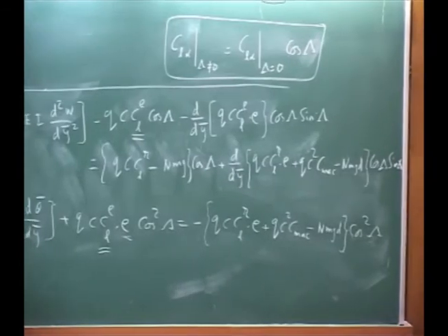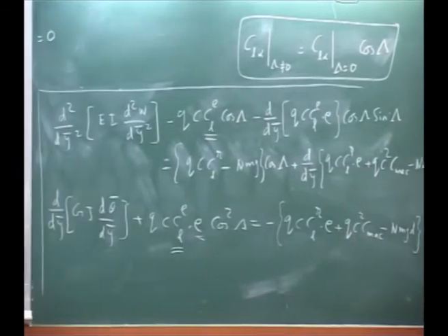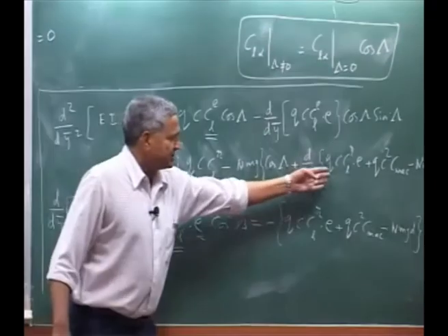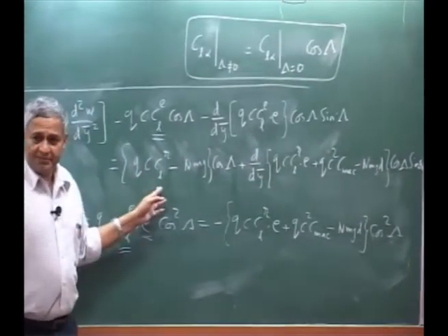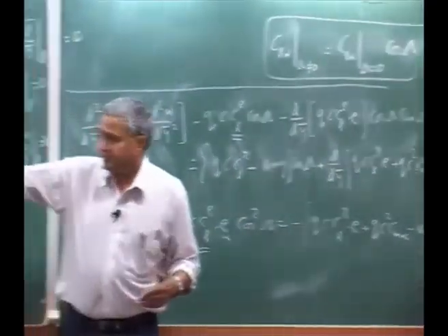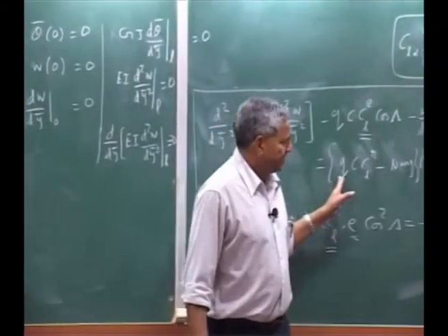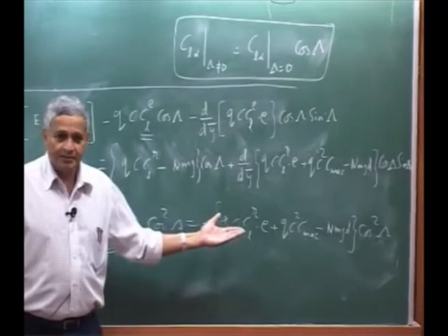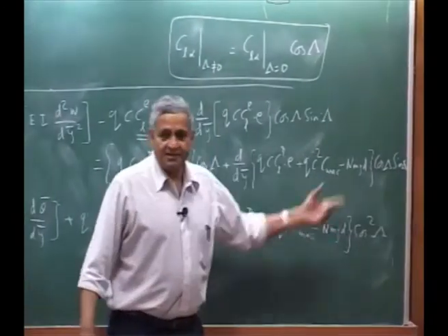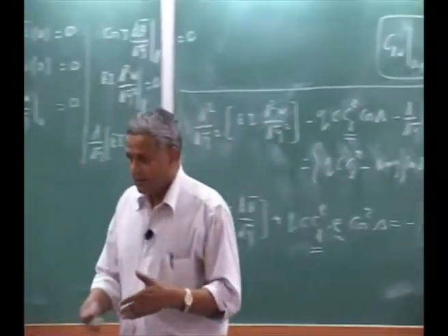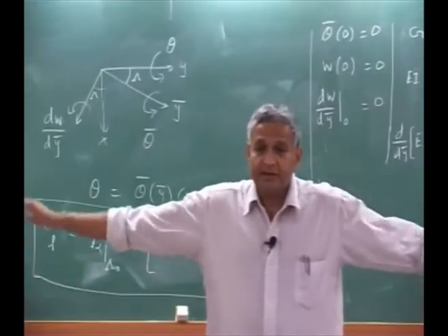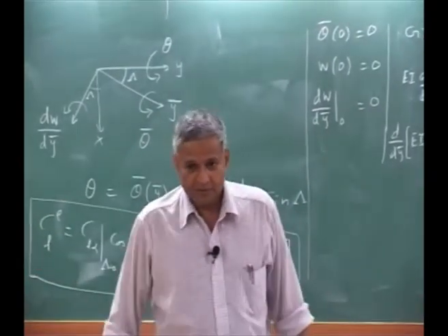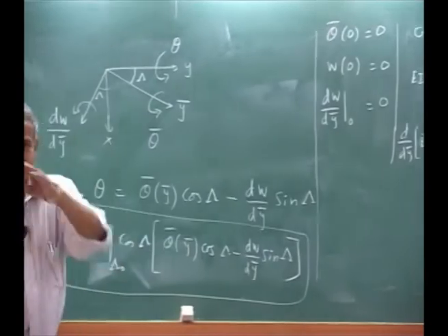Otherwise you can solve the elastic deformation also. That means for the elastic deformation, you put what is the rigid angle of attack, what is the dynamic pressure Q, then you have all these properties, and if it is a level flight, n is 1, and with the distribution of mass, you can find how the wing deforms. Okay?